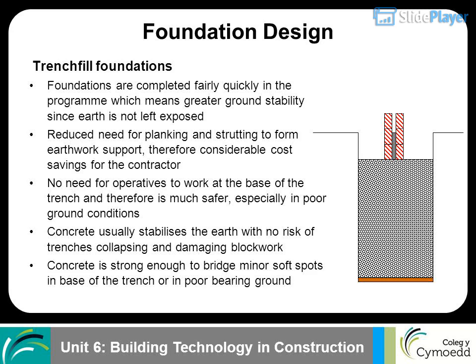Foundations are completed fairly quickly in the program, which means greater ground stability since earth is not left exposed. Reduced need for planking and strutting to form earthwork support, therefore considerable cost savings for the contractor. No need for operatives to work at the base of the trench and therefore it is much safer, especially in poor ground conditions.